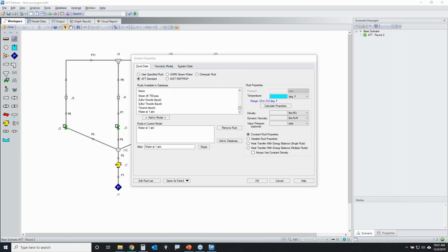Another troubleshooting technique is, if you're using heat transfer and you're having troubles getting convergence, again, just do one of your troubleshooting steps in your child's scenario where you set it back to constant fluid properties. That eliminates all that complexity where you can just focus on hydraulics. Those are all things that will help pinpoint what the issue might be that's causing the model to not converge.